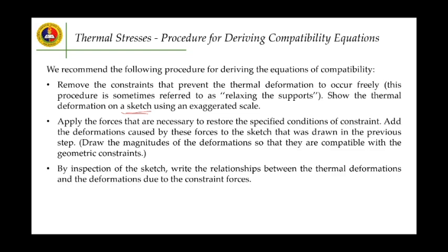Therefore, the use of diagrams and sketches will really help. Next, apply the forces that are necessary to restore the specified conditions of constraint. Then add the deformations caused by these forces to the sketch that was drawn in the previous step. Now draw the magnitudes of the deformation so that they are compatible with the geometric constraints.